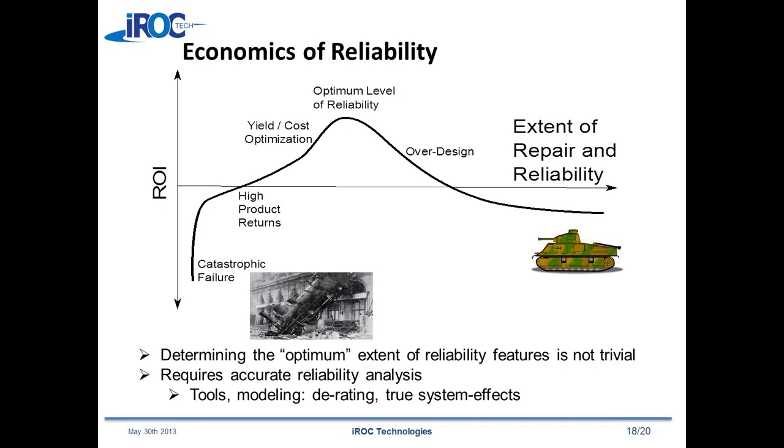I like to think that there's some sort of optimal level of reliability for a given application. As you start to cut corners, you're going to increase the number of errors that happen in the field, and depending on the application, that's going to mean an increased field return rate. That's going to have a cost. One thing to bear in mind is that often when a soft error event occurs in, let's say, a server card or a router card, there's no clear diagnosis saying, oh, a soft error happened in the flip-flop, that's a good card, just reset it and leave it.